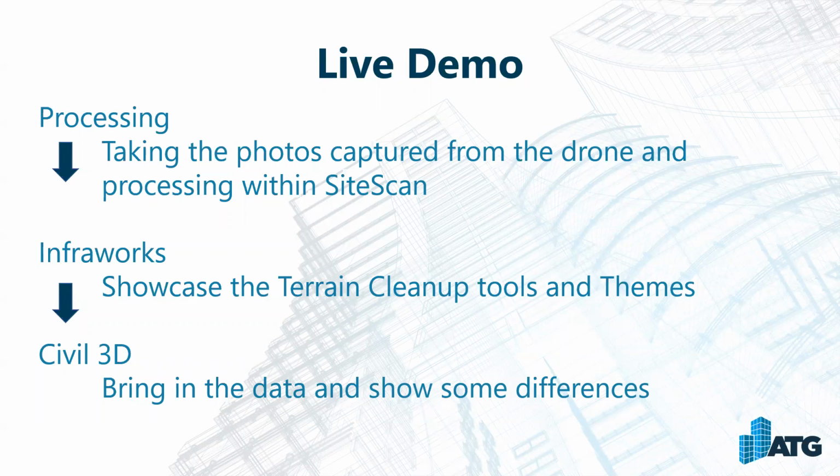So we'll be diving into SiteScan, and I'll show you some of the features with that, but just keep in mind that's not the only location where you can process your drone data. And then we'll jump into Infraworks. We'll showcase some of the terrain cleanup tools and some of the point cloud themes that we can assign. What's really cool about those is they will translate right over into Civil 3D. And we'll show some differences of going straight from drone-processed data into Civil 3D, or going through Infraworks.